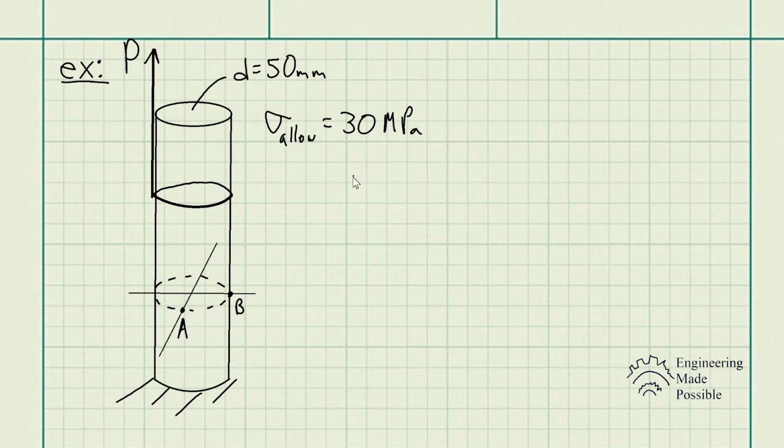So this is another case where you're going to have an axial stress, but additionally, since this is offset from the center of this rod, it's also going to cause a moment. So you're going to have the axial stress plus your bending stress, and this is equivalent to the total stress going to be developed in this rod.